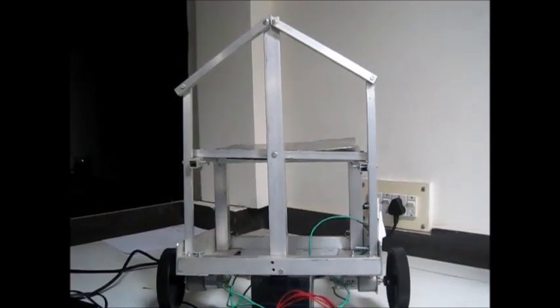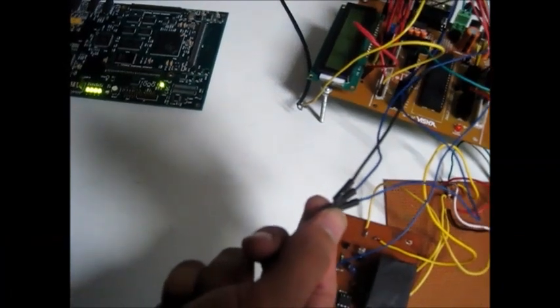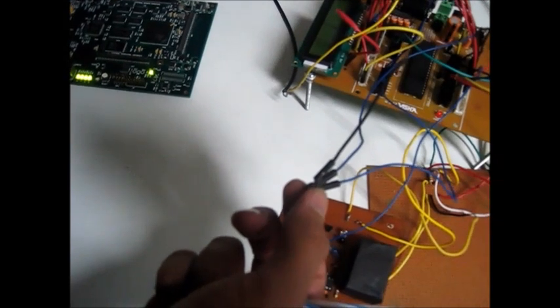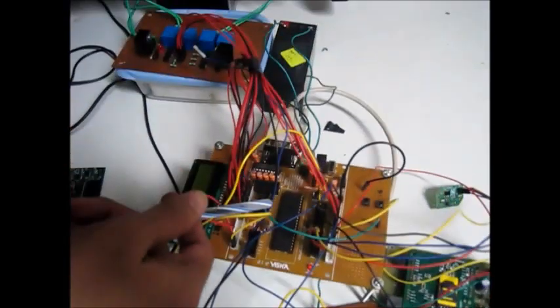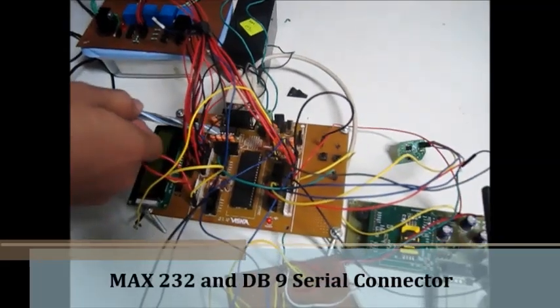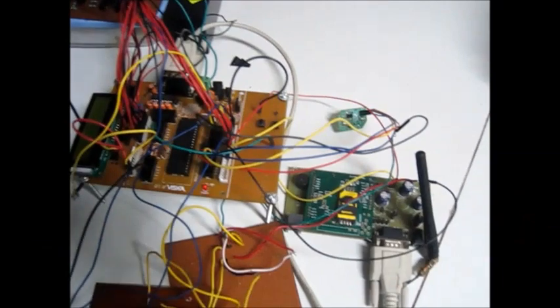The patient monitoring system is interfaced with the ATmega16 microcontroller along with the GSM module. We have used the LM35 temperature sensor from Texas Instruments. It is a precision centigrade temperature sensor which has a resolution of 10 millivolts per degree Celsius. The communication between the microcontroller and the GSM module is achieved via the MAX232 IC from Texas Instruments and a DB9 serial connector.